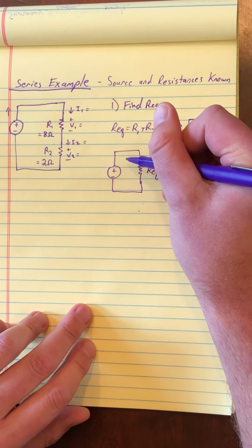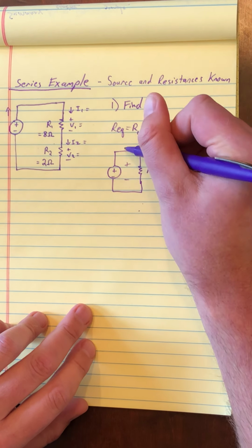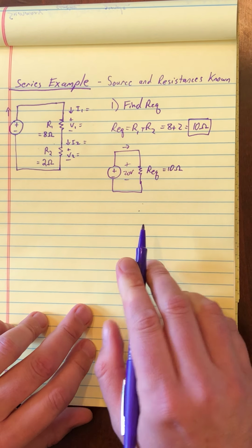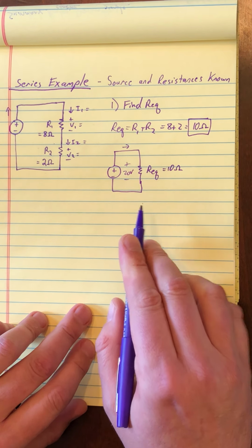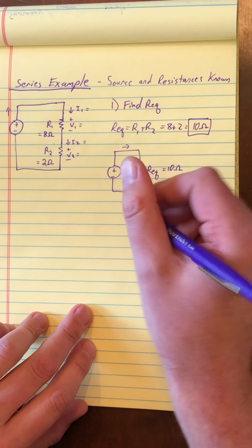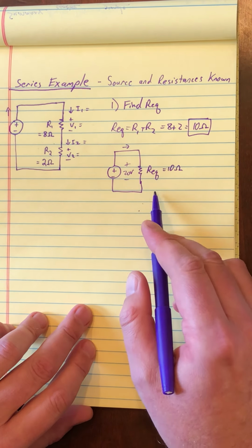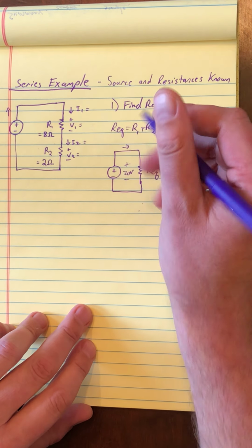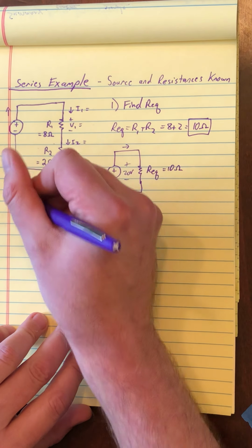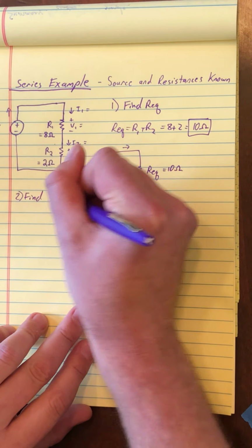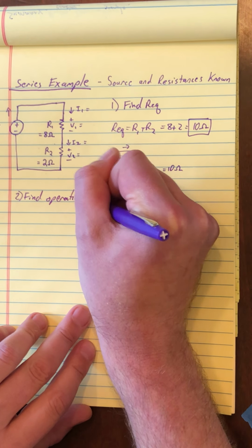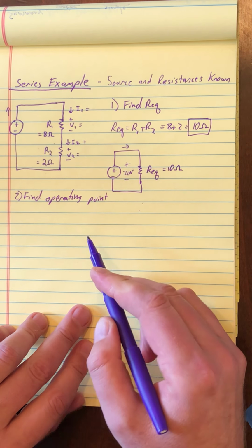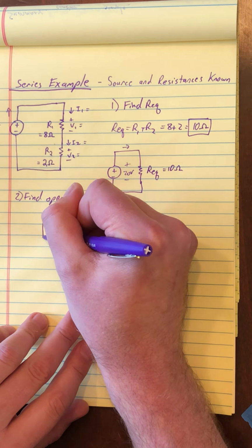And so since these now will share the same voltage and the same current, and I already know that the voltage here is 20 volts, I can use this to find my operating point. We can do this using our element equation or looking at the graph for the IV characteristic. And when I say operating point, I mean what is the source current and voltage on our IV characteristic. And so here it is.